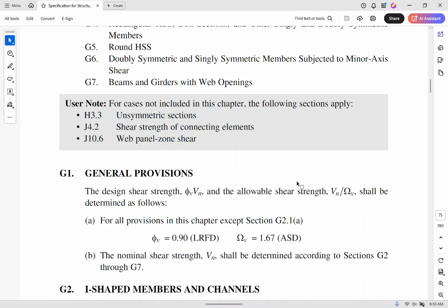Now let's read what this says. For all provisions in this chapter except section G2.1(a), this is our phi value. And then what it says is, phi v and vn, this is the thing about phi v and vn, shall be checked for all this other stuff. So let's start here. For all provisions in this chapter except section G2.1(a), phi is 0.9. I don't know about you, but maybe we ought to look at section G2.1(a). So let's take a look at it.